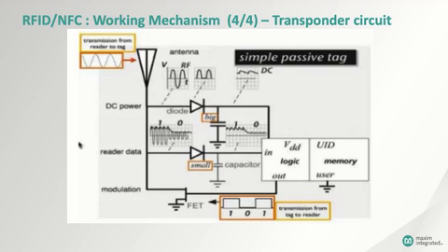When the tag logic receives a command that requires a response, it begins sending the encoded bit stream to the FET to modulate the load on the antenna. The antenna, actually the secondary coil of a transformer that's made up of the reader coil and the tag coil, is opened or shorted according to the encoded bit stream coming from the tag logic. This bit stream induces current variations in the primary side of the transformer that's in the reader.